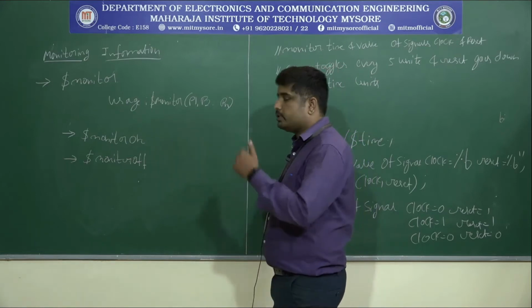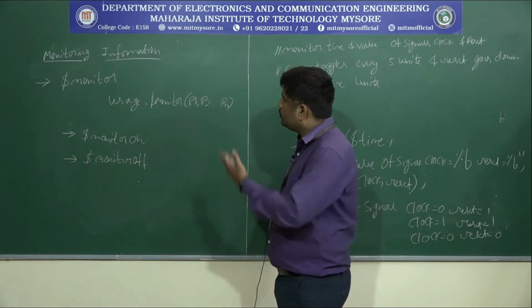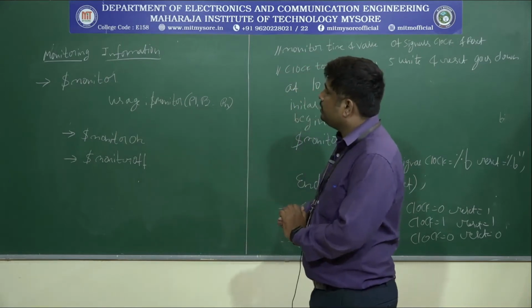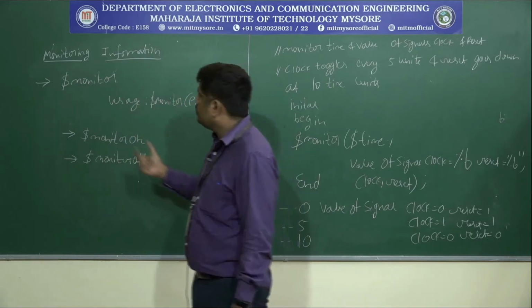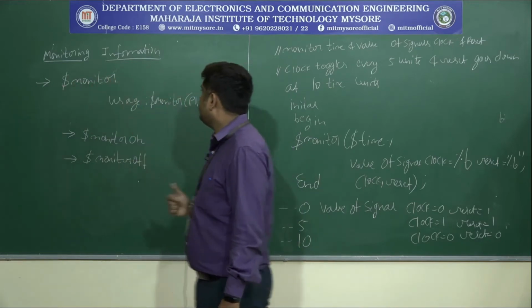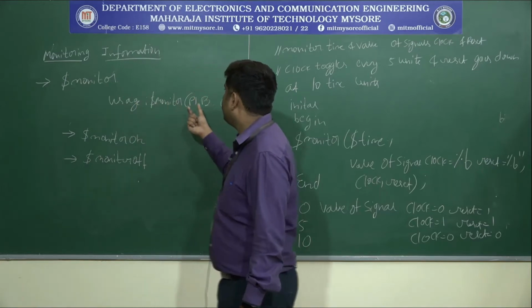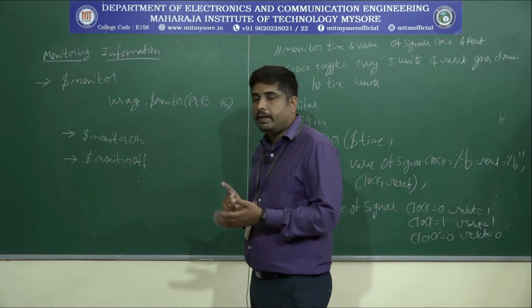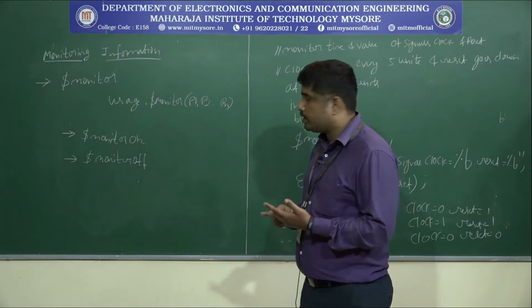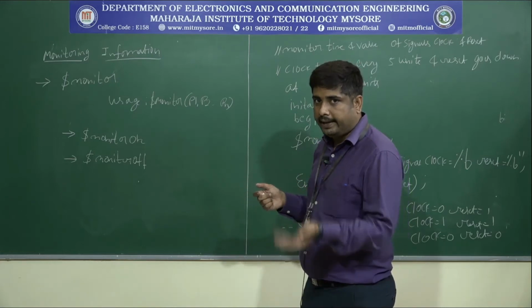Next, once you display the information, you need to monitor that information. So next, monitoring information. The keyword is $monitor. These are some examples. Usage: $monitor(P1, P2, ..., Pn). P1, P2, Pn may be variables, constants, or strings, depending on the example.